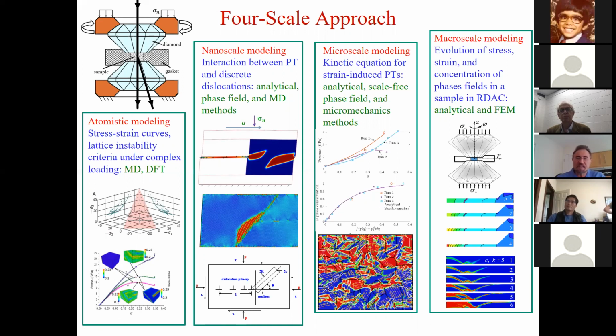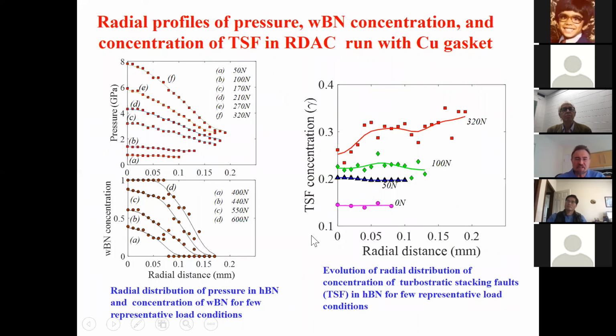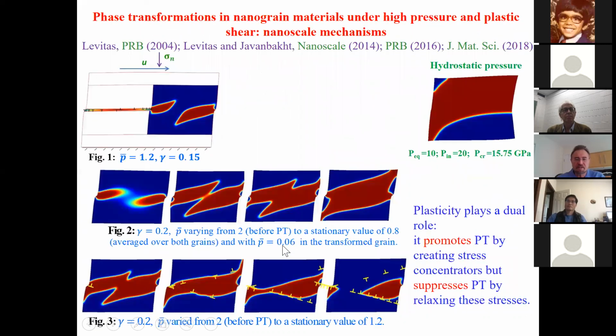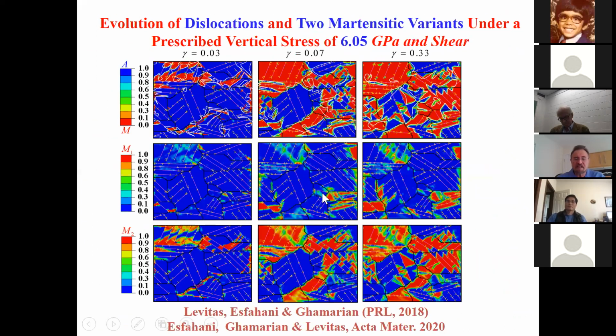If you have sliding, for example, here, this is scale 3. Let me show this model again. This is scale 3. It can be kilometer by kilometer, but these are localized shear bands. They also produce a similar stress concentrator. If you have sliding of one piece with respect to another within bulk material, it produces a stress field equivalent to a dislocation pile-up.